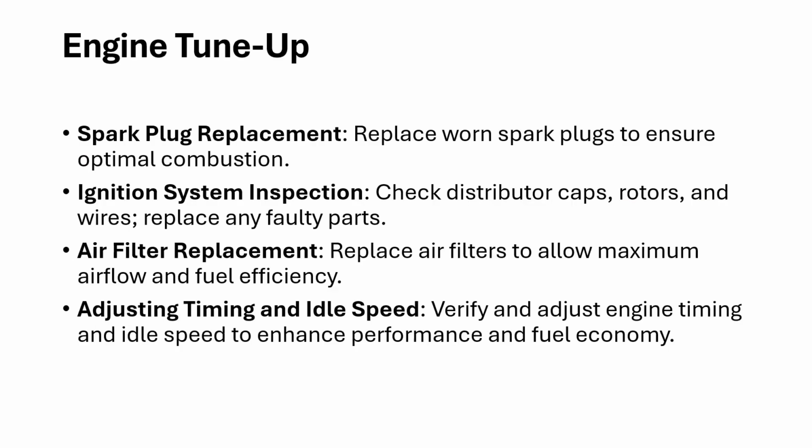Engine tune-up is part of the fuel system, we can say. We have to replace spark plugs if they are worn, to ensure smooth and optimal combustion operation. For ignition system inspection, we have to check the distributor cap, rotor, and wires, and replace them if there are any faults.